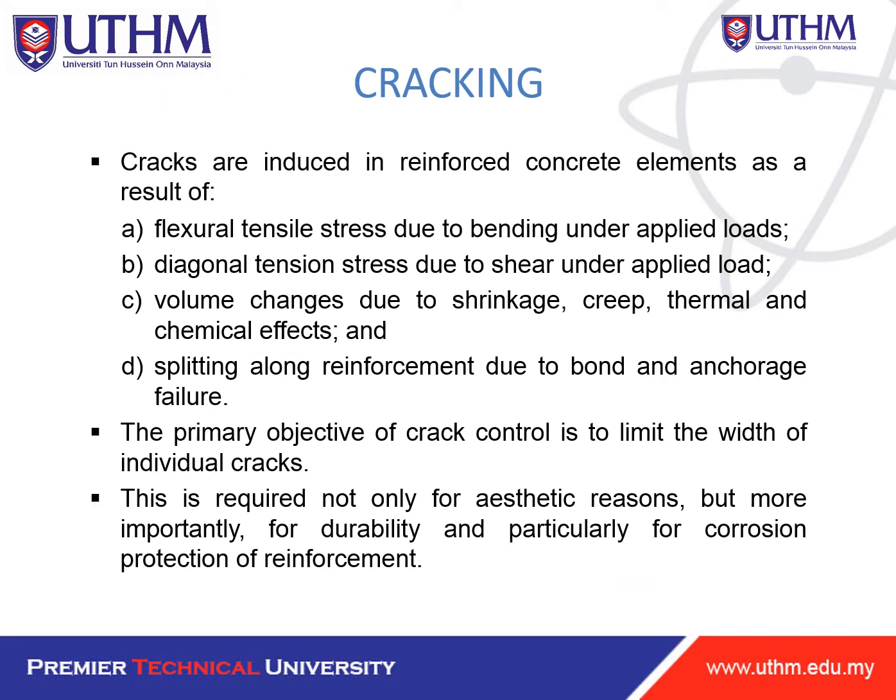So let's look at cracking. Cracks are induced in reinforced concrete elements as a result of, first, flexural tension, which is tensile stress due to bending under applied load; diagonal tension stress due to shear under the applied load; volume changes due to shrinkage, creep, thermal and chemical effects; and splitting along the reinforcement due to bond and anchorage failure. The primary objective of crack control is to limit the width of individual cracks. This is required not only for aesthetic reasons, but more importantly for durability, particularly for corrosion protection of reinforcement.